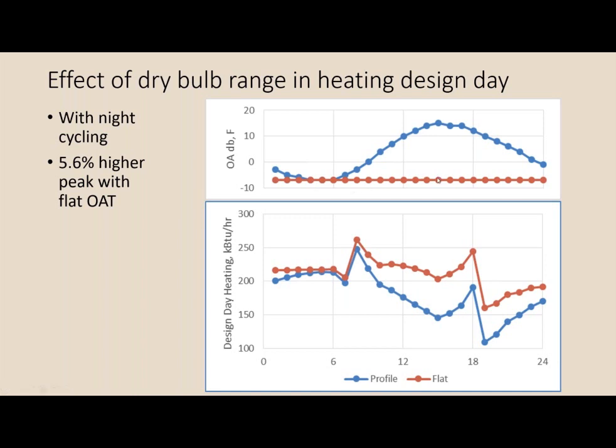so I'm doing two different simulations. One with that held flat, so I'm setting the range to 0, and the other I'm setting the range based on what I found in the weather file, which causes it to go from -8 to +15. So the range is about 22 degrees. So the entry into DOE-2.3 would be 22 degrees for the daily range. The result of that difference is shown down below.